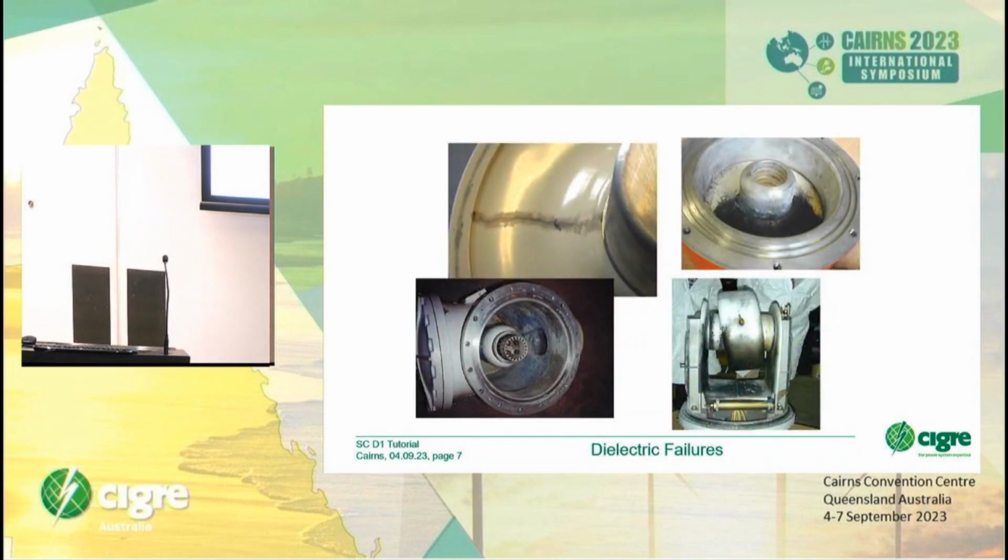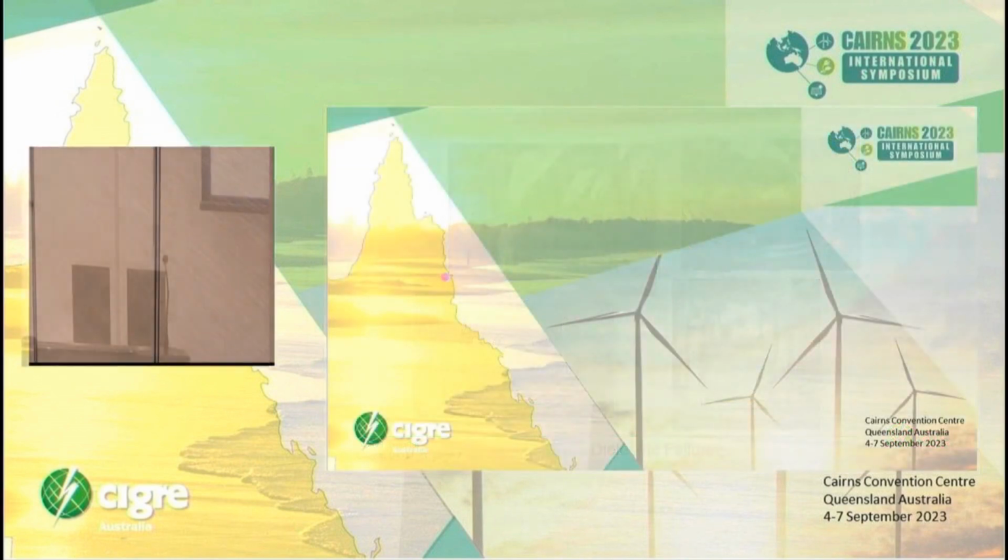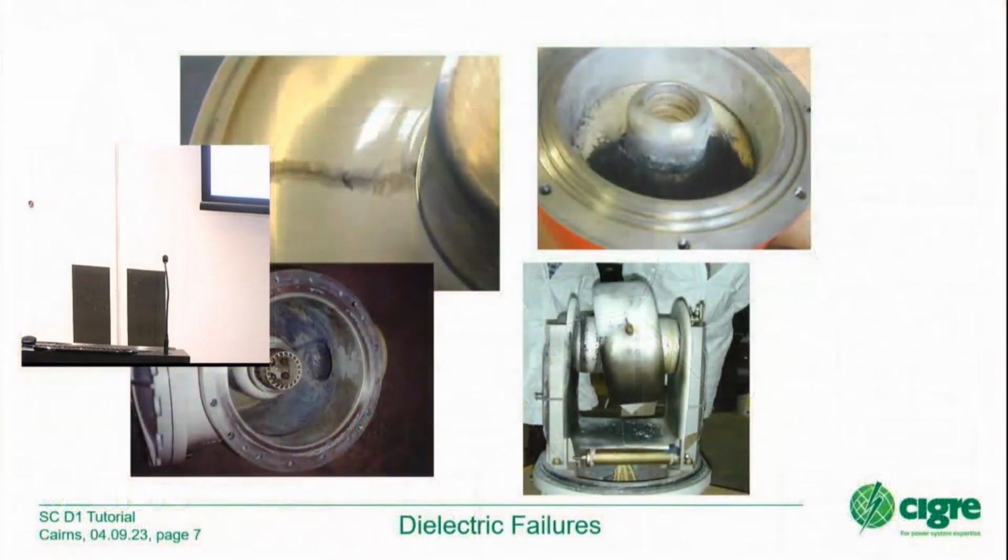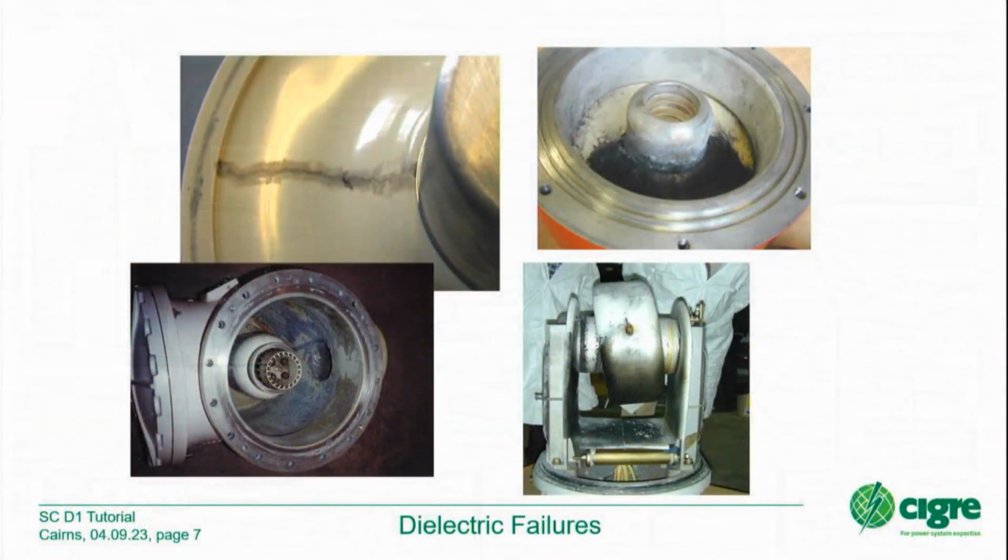What we would like to do with our partial discharge measurement, and in detail with the ultra-high frequency partial discharge monitoring systems, is to avoid such pictures. All these pictures are showing flashovers and power arcs. Here we have a flashover on the surface of an epoxy spacer. Here, shortly before repair work, a flashover at a 90-degree angle, a power arc of maybe some 30 kiloamps for 100 milliseconds in the compartment, and here a damaged voltage transformer.